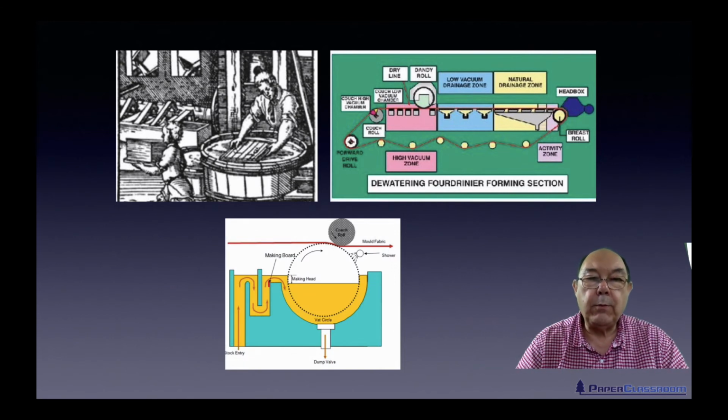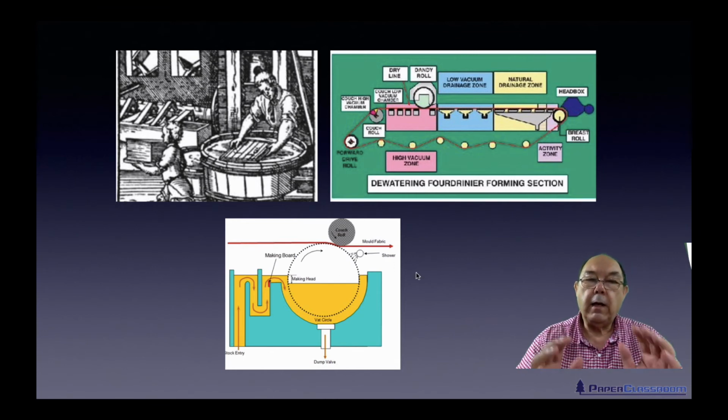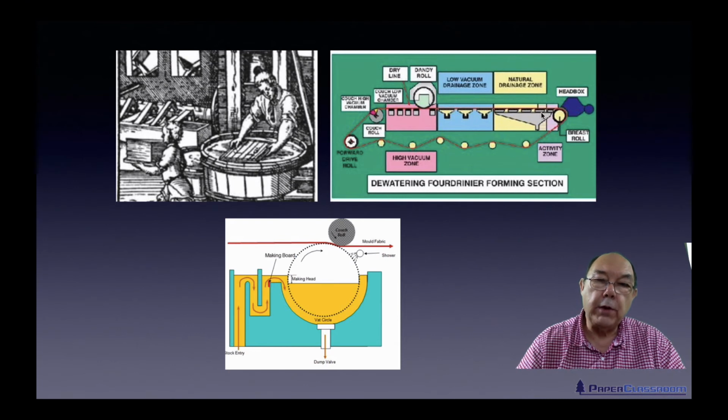While the Fourdrinier machine was being developed down at Frogmore Paper Mill, on the plot next door to the people who were doing that was another gentleman by the name of Dickinson, and he was inventing the vat machine. So rather than a very long continuous wire where you were squirting fibre onto the surface, here you've got a round vat machine, and the water and the fibres are sucked through the wire. The water goes through, the fibres are deposited on the outside, and away it goes.